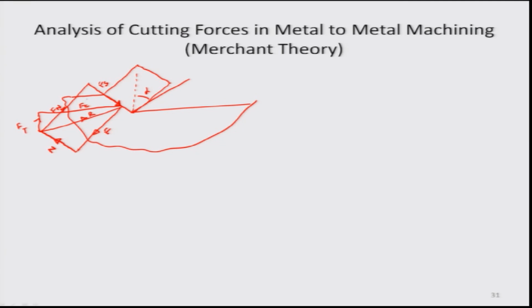Okay. So, having said that, obviously the normal force on the shear plane due to which the normal stress would probably come up is because of this Fn value right here, and the area of the zone, I think, which we had done earlier was actually W t1 by sin phi.